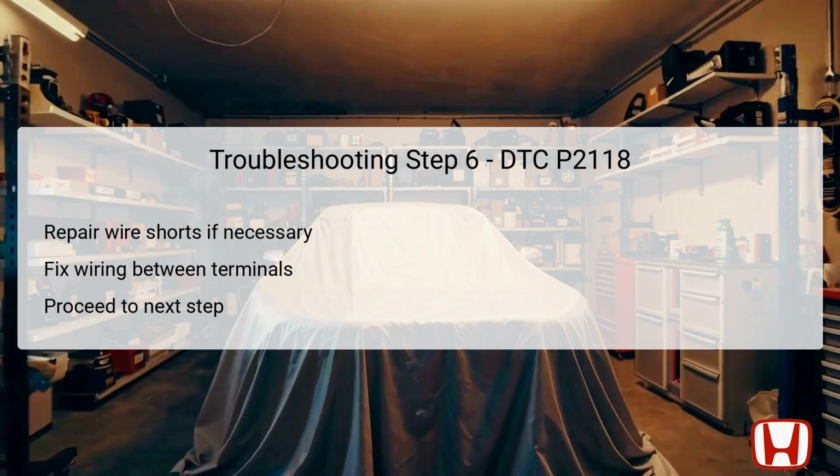proper electrical flow. Once the repairs are made, follow this up with continuity tests to confirm that the repairs have resolved the issue. After verifying the integrity of the connections and resolving any wiring issues, you can advance to the next diagnostic step to evaluate the throttle actuator itself.